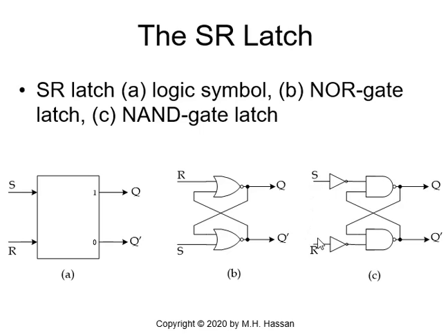We are applying 1, 1 here, so the NAND gates will have zeros at their inputs. So 0 NAND 0, you will get 1, and 1 NAND 0, you will get 1. So you'll have 1 here and 1 here. If we repeat the cycle again, 1 NAND 0, you will get 1, and 1 NAND 0, you will get 1.